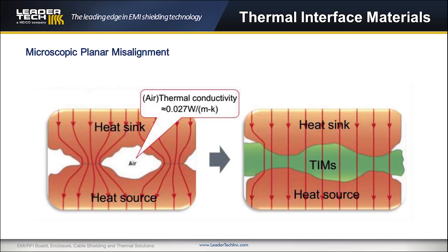Enter thermal interface materials. They eliminate air gaps and increase the heat transfer between two mating surfaces. They conform to uneven microscopic mating surfaces, allowing heat to flow from one surface to the other in order to reduce the overall temperature of the device in which the gap is applied.